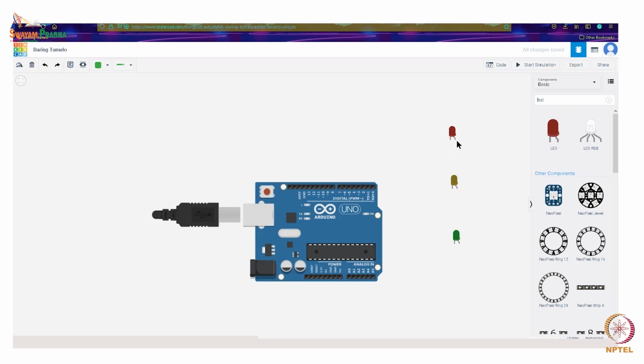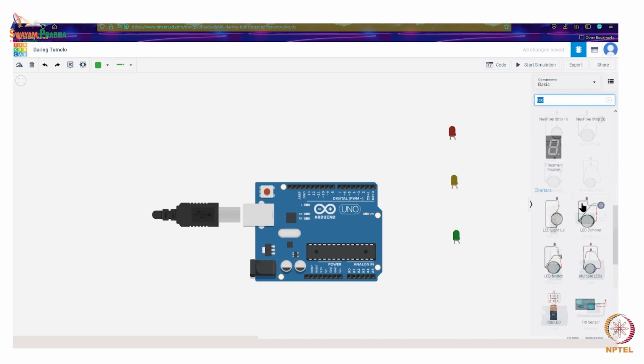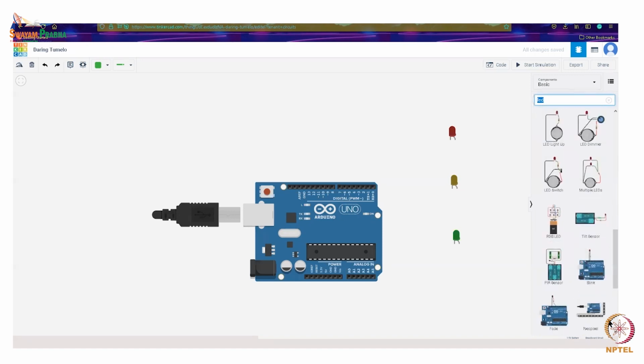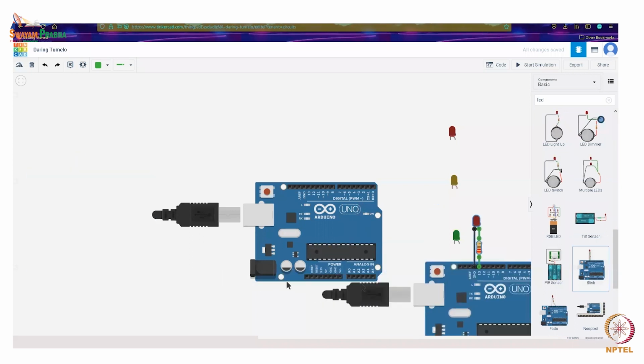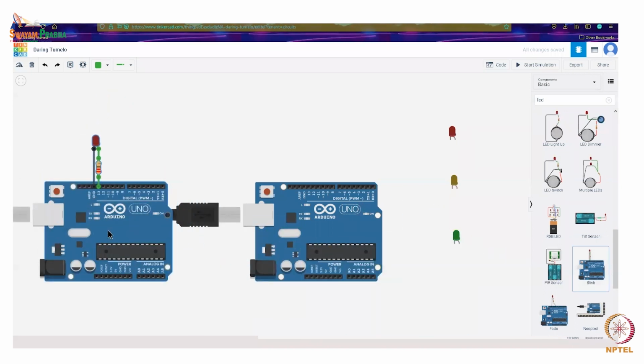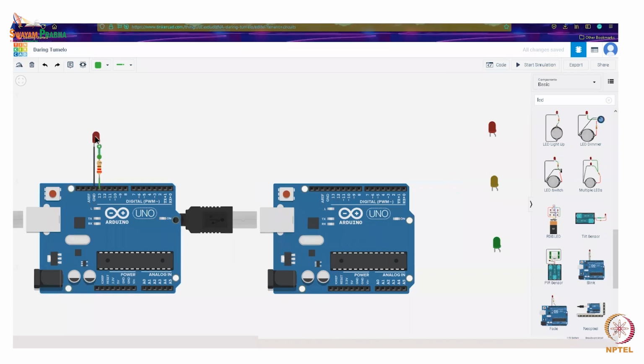So we have two parts. One is the anode and the second one is the cathode. For the LED glowing, we already have an example actually in the Tinkercad. So in the practical scenario, we need to connect a resistor to prevent overloading on the LED system. But in the current case, we can just skip the resistor part. So if you see, we have two parts. The ground is connected to the cathode, and the voltage is connected to the anode.